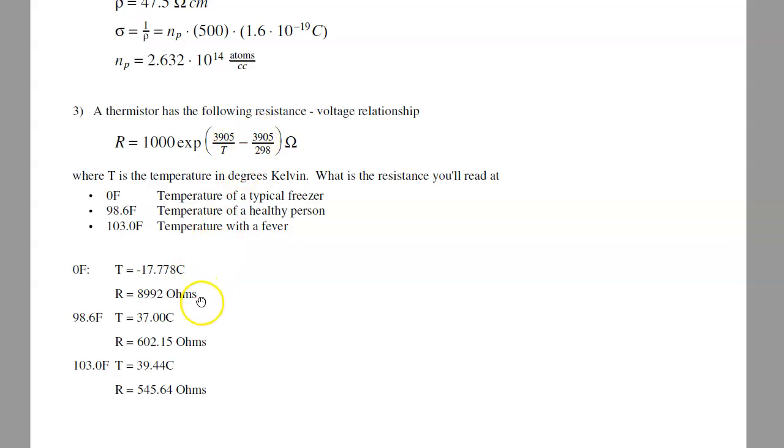Plug it in. I get 8992 ohms. I warm up to 98.6, 605 ohms. 103, 545 ohms. So if I can measure resistance, I can tell you temperature.